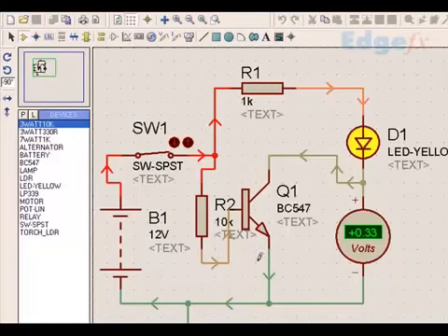And once the current starts flowing, these 2 points are just like a switch. Just like a switch means once the switch closes, the voltage drop across this is nearing 0, just the switch drop, or the saturation voltage drop we call it. And since this particular point comes to ground, it is nearly 0 volts.